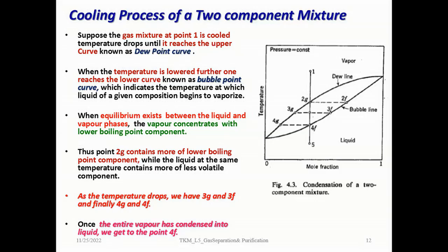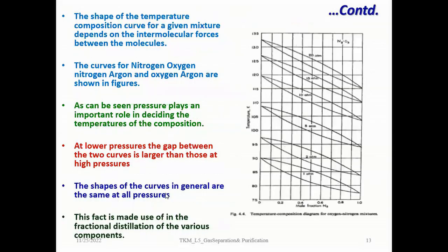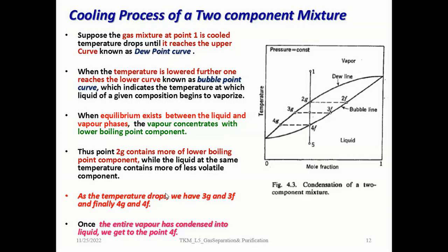Now, what does it show? It shows that as you cool down through this dew line and bubble line, the liquid phase enriches in the high boiling point component, and the vapor phase enriches in the low boiling component. This is exactly what happens during the process of cool down, because the dew line and bubble line are separated for a gas mixture. Right, let's proceed further.